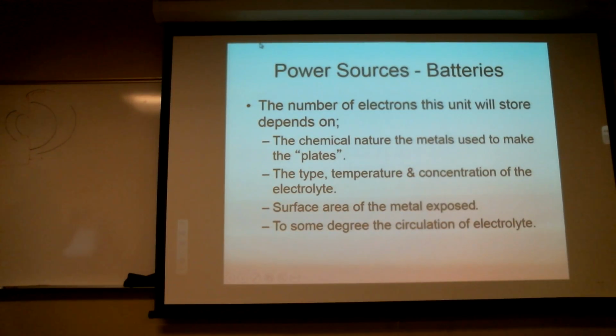So we're going to design the battery quite a bit differently for different mission profiles, right? That means other characteristics are going to be how much current it can give in the short, immediate, boom, boom, boom, versus how well it does being very deeply discharged and then recharged and not falling apart.